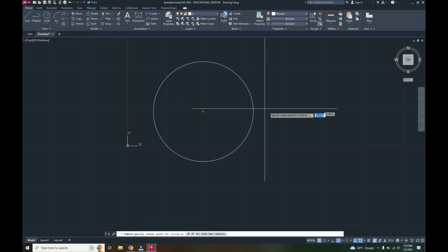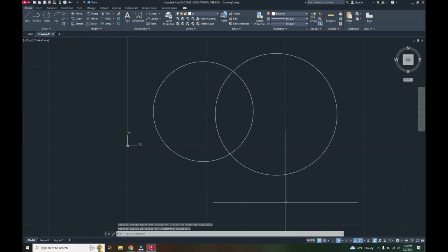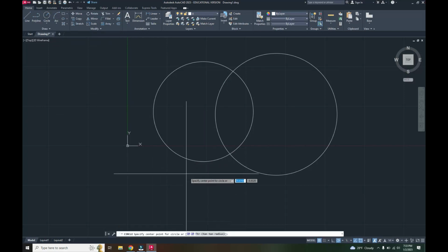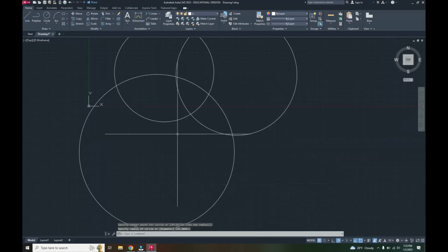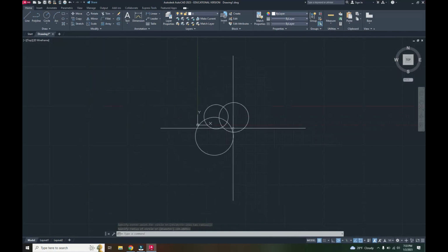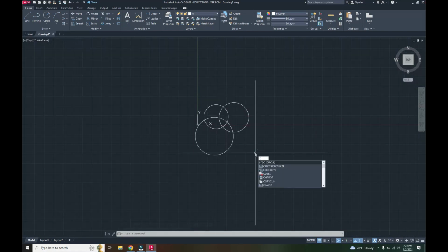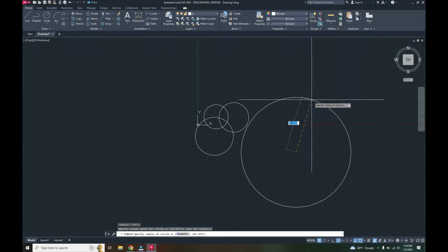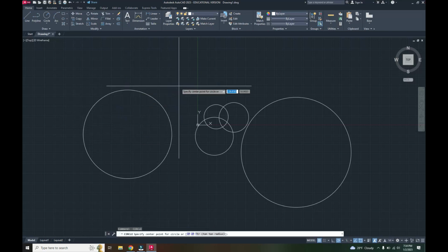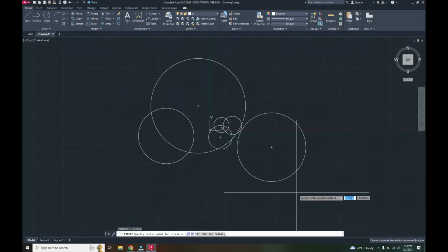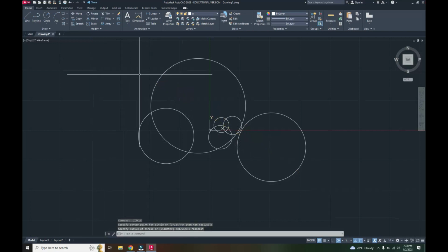And same thing again here, circle tool, click and drag, and I can make lots of separate circles here. Make a little Venn diagram. Now with my circles, I can also type in C for circle, and you could type in circle all the way if you wanted to. Hit enter, and then I could go for a circle. And I can start that command again by hitting the space bar and going again. Space bar, go again, and now I have lots and lots of circles.